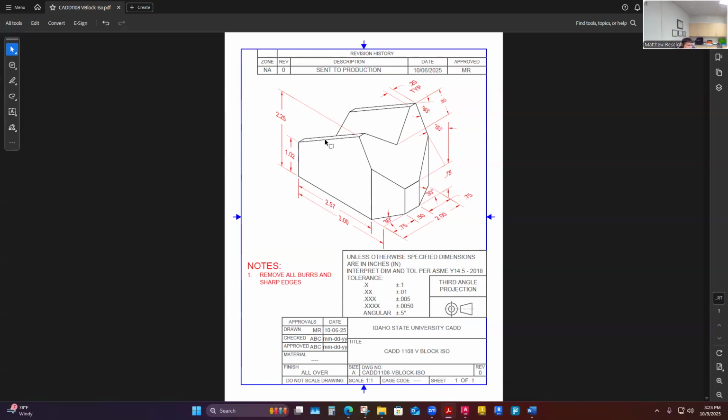That'll be a true length. It'll be right perpendicular to my eye. The surface and that line will look just as the true length that it really is. And so will this 102, and so will this 257. What won't is this surface. In my front view, I'll see it, it'll just be foreshortened for me.